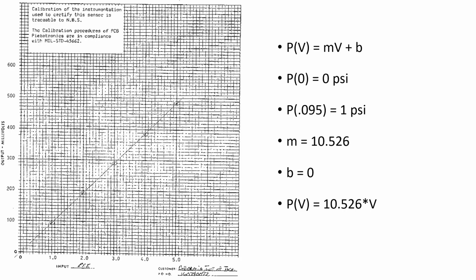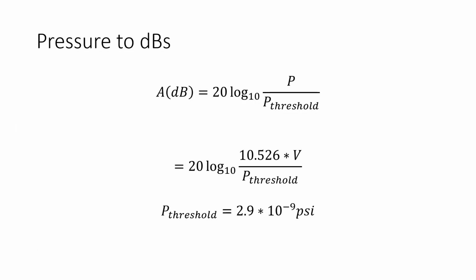Now we have collected data from both the piezoelectric transducers and the photomultiplier. However, the data from the piezoelectric transducers is given in voltages rather than what we need, which is pressure. So, in order to convert from one to the other, we use this calibration curve, which shows a linear relationship between pressure and voltage, which makes it fairly easy to convert from one to the other, as shown here in this equation.